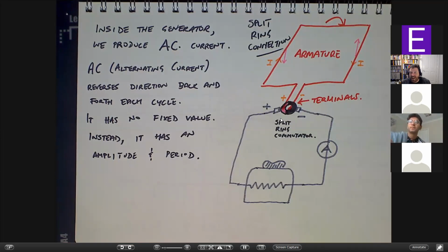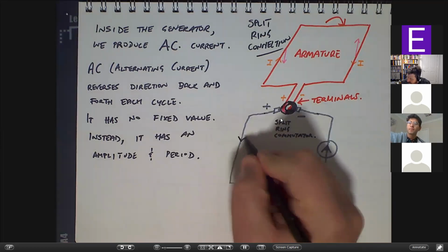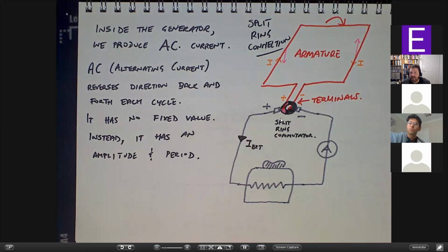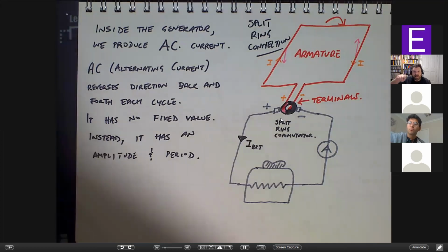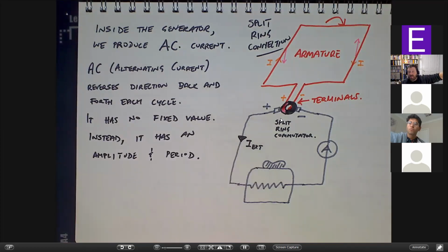So we're not actually going to have AC electricity coming out the other side. We're going to have electricity which is always going from positive in this direction. So I external is always going to be going in this direction. Now the magnitude of that current is still going to be bouncing up and down as a function of the magnitude of the potential, but the direction, just like in a DC motor, gets changed every 180 degrees by this split ring commutator to keep it constantly positive.